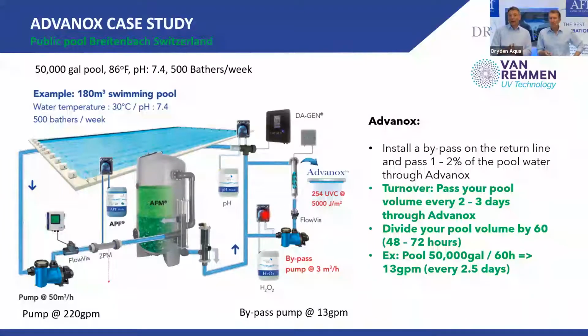You have to know, do I have 30 gallons per minute, or do I have 30? Otherwise, we don't have the right dose anymore. And the dosing pump for your peroxide: a small one, the same that we use for flocculation. Because you have to dose this peroxide permanently. It's not helping if you dose 1 minute and then you stop for 59 minutes. You have to dose it continuously. Small, but permanent. Yes, continuous dosage.